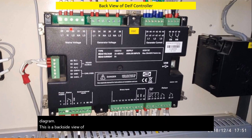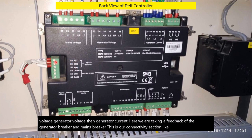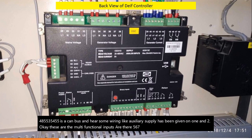This is a back side view of the controller, and we see that here we are sensing the mains voltage, generator voltage, then generator current. Here we are taking feedback of the generator breaker and mains breaker. This is our connectivity section: 49, 50 and 51 is RS485, 53, 54 and 55 is CAN bus, and the auxiliary supply has been given on 1 and 2. These are the multifunctional inputs, 5, 6, 7, 8, 58 and 59. These are the binary inputs, which are nothing but digital inputs.